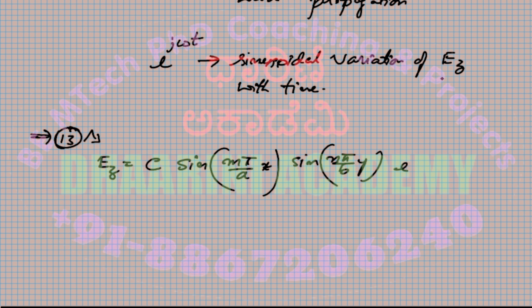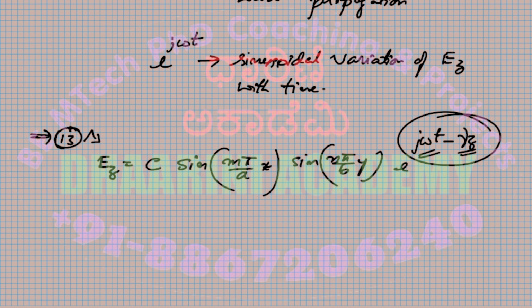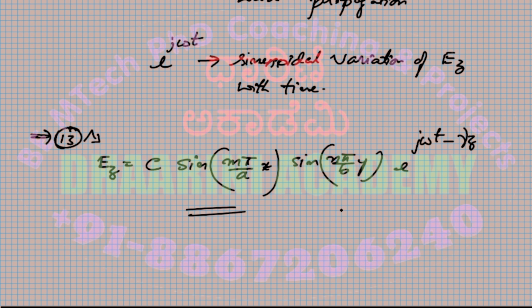You see, we are trying to club the two terms. One is the j omega t, which is positive, and the gamma z, which is negative: e to the power j omega t minus gamma z. Because e to the j omega t into e to the power minus gamma z, we club it. Now you see e to the j theta, and this itself is represented as your phase component. You told we might need a phase as well, so the solution to the phase comes from this side.